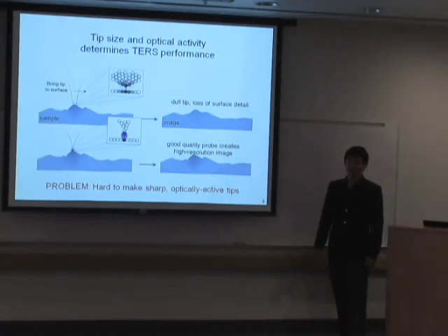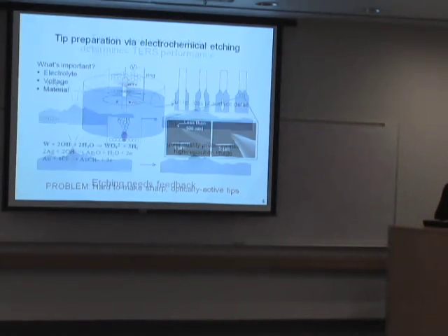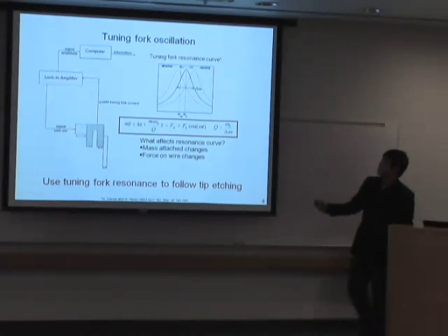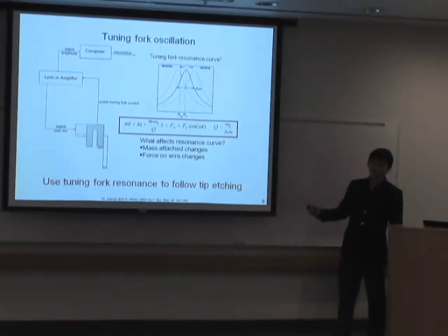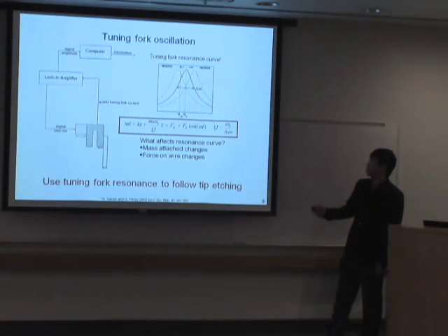And that frequency, as you see in the resonance curve, let's go back here, this resonance curve, it only vibrates with a high amplitude at that specific frequency. So even if you excite it at a different frequency, say here, it's not going to be very useful because the resonance frequency is right here.